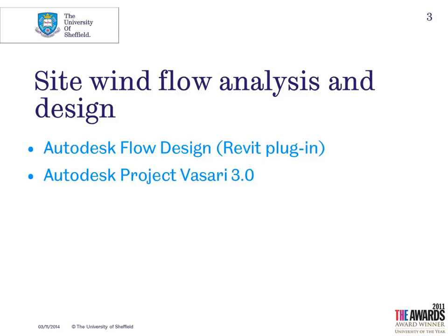Okay, so the first thing to say is the Autodesk Flow Design. You need to download that for free from your normal Autodesk education site. What it then does is it downloads it as an application onto your hard drive, which will come up as Autodesk Flow Design, but also in the background it should install it into Revit as a plugin.